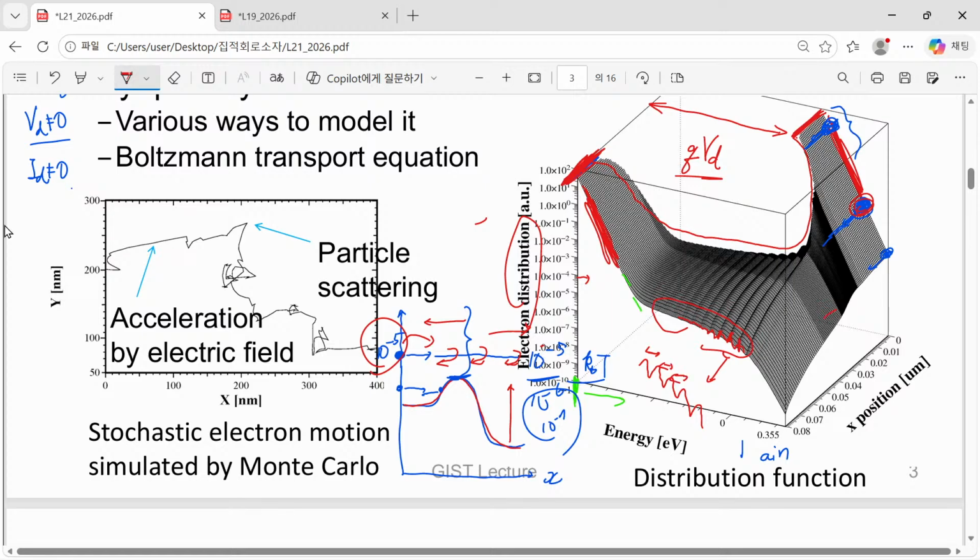And this energy difference in silicon material is given as about 60 milli electron volt in this case. Please don't be confused with 60 millivolt per decade. This is nothing related to the subthreshold swing. This is 60 milli electron volt energy.